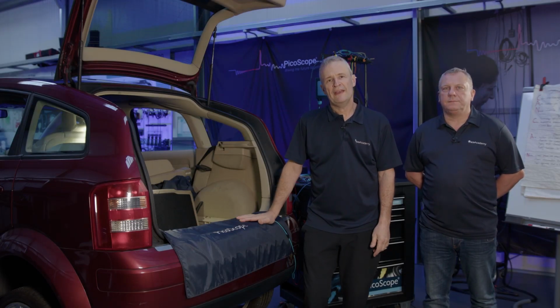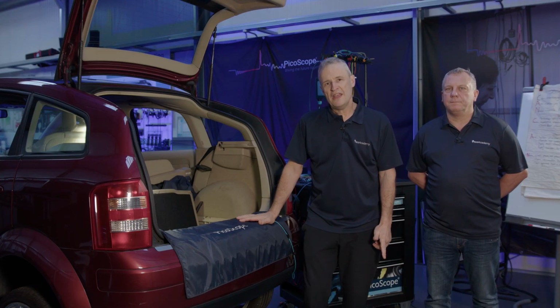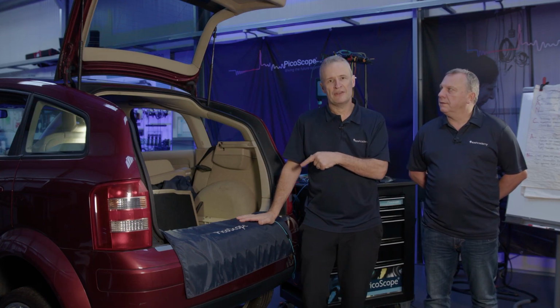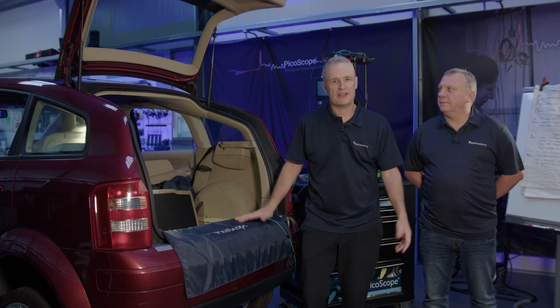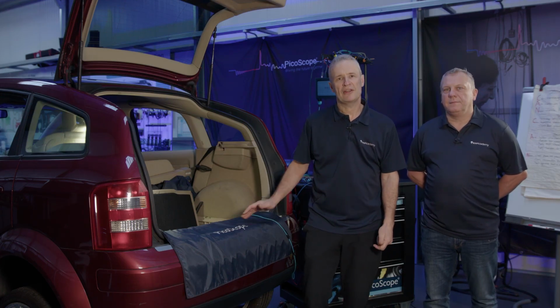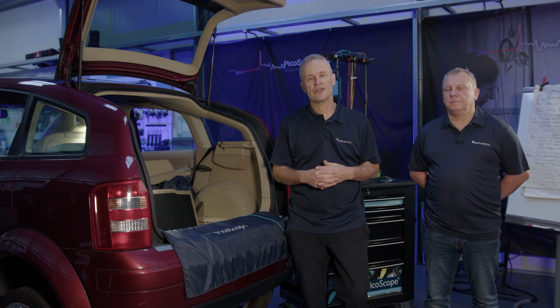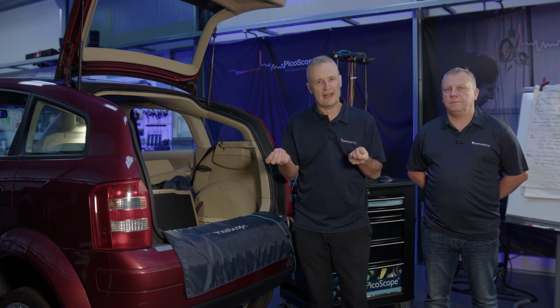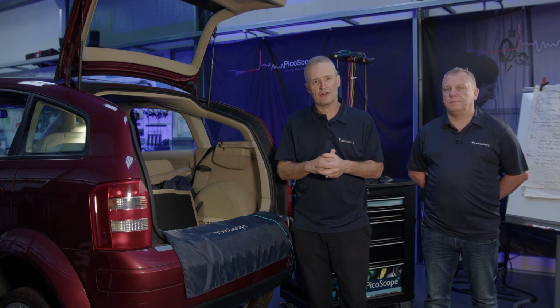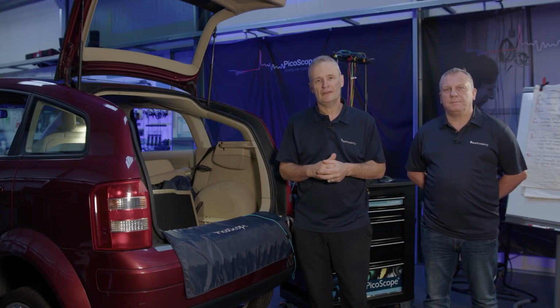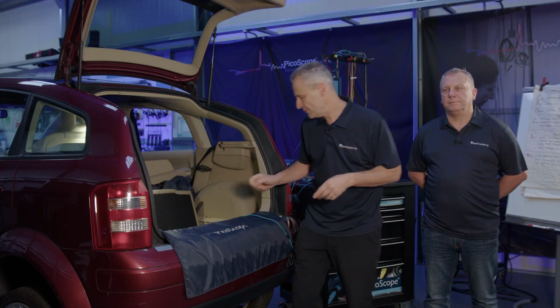Okay, so following the CAN principle, can messages be sent? We're going to actually skip this bit about disconnecting the battery, because what is there other than disconnecting the battery? And that was until I checked to see whether there was any potential between the two leads. So disconnecting the battery positive and negative, just put the voltmeter across there, the scope. Sure enough, it isn't 0 volts. So let's just run through that and see what we have to do to ensure this vehicle is totally at 0 volts. So we'll disconnect the battery.